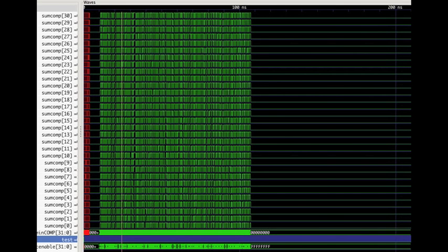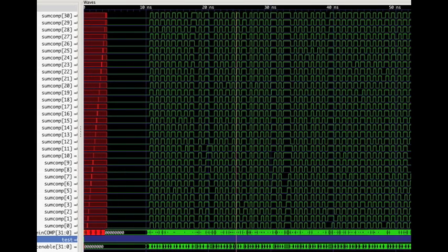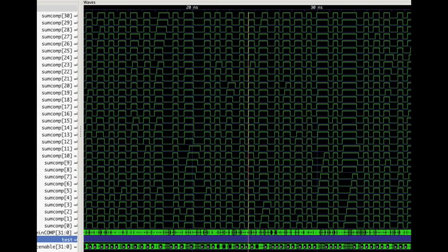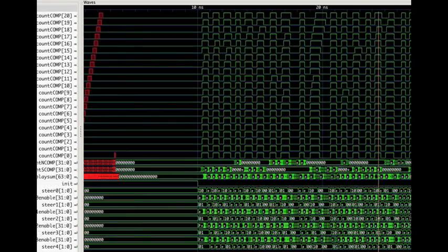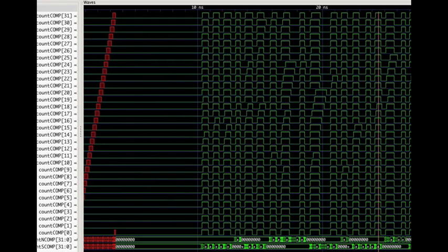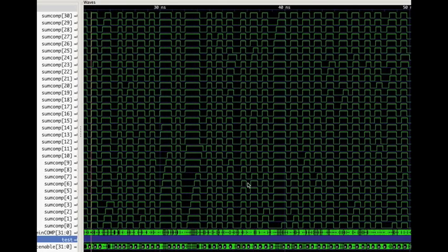Okay, so now we go to the ragged wavefront input, and the input here was from the adder with the variable carry chain delays. And you can see some of the carry chain delays at the output of the shifter. This was the input. This is the output of the adder, and you can see the carry chain delays at the output of the adder. And this is the output of the shifter relating to the carry chain delays.